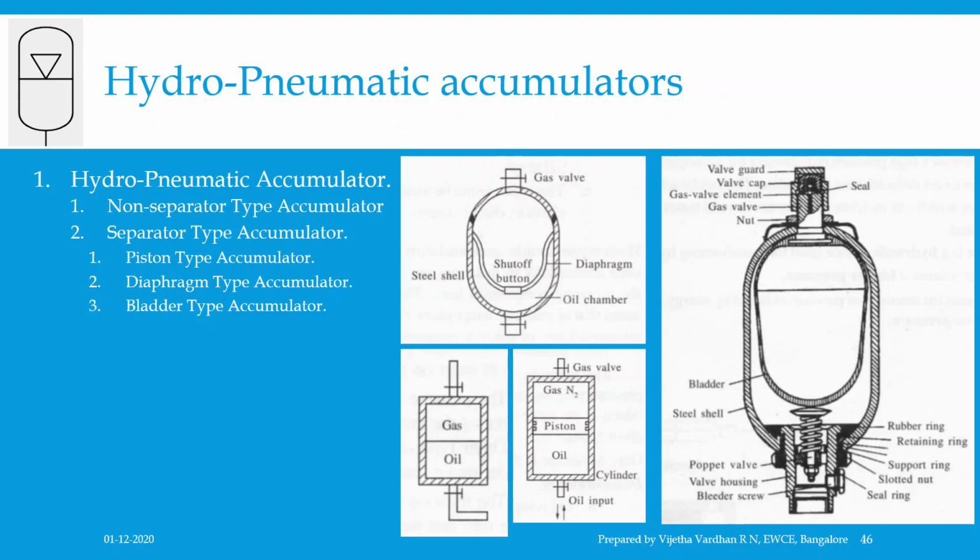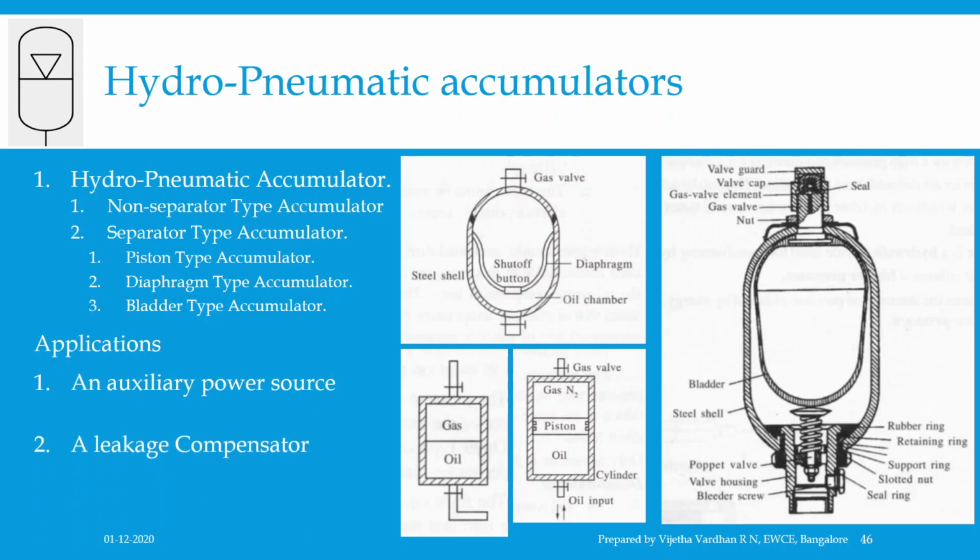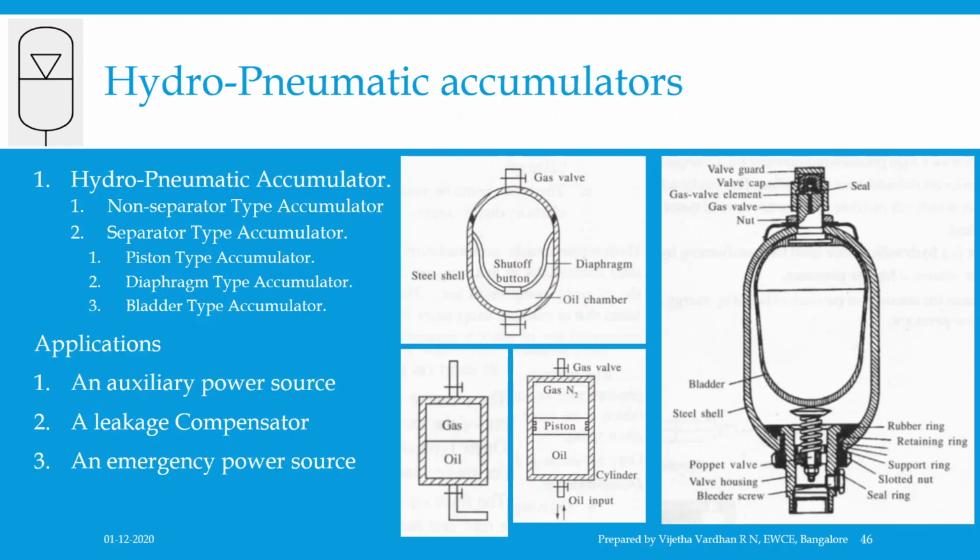also shock damping applications. Then coming to the applications of the accumulators, from the application point of view, accumulators can be used as an auxiliary power source, or it could be used as a leakage compensator, and even an emergency power source and a hydraulic shock absorber.